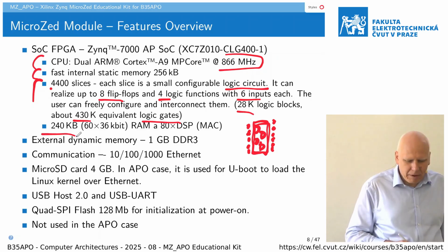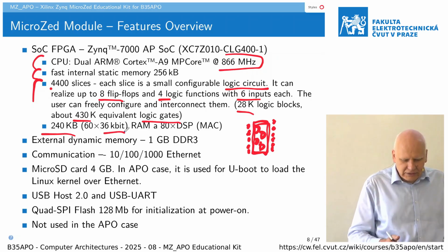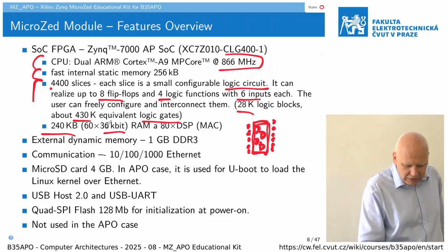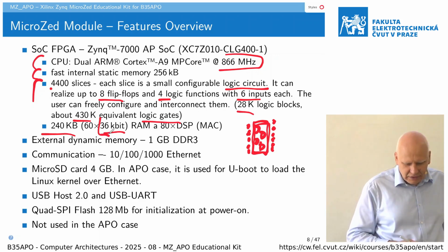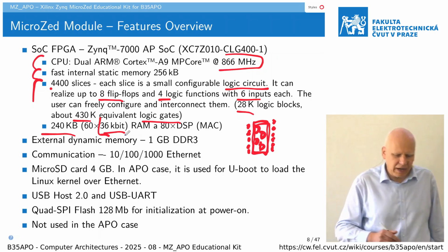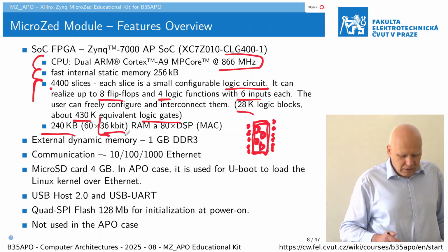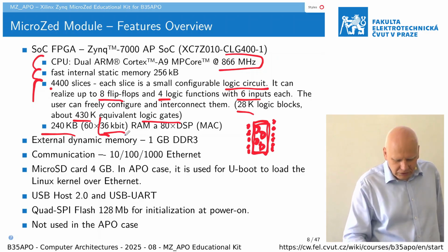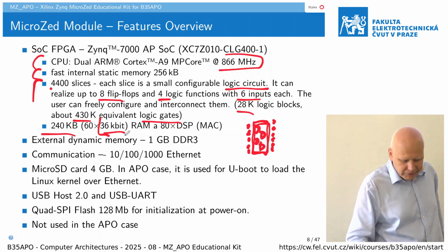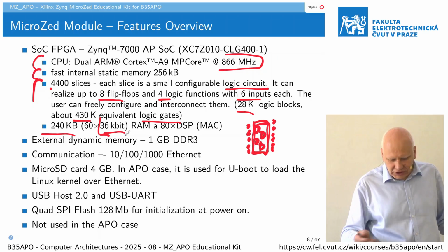There is some amount of distributed memory inside of this chip, so it is organized as 36-bit wide, but it can be reconfigured even to different sizes, and it is fast, and it is with double input-output ports and so on, dual ports, so it allows to implement some interesting functionality, caches and so on.